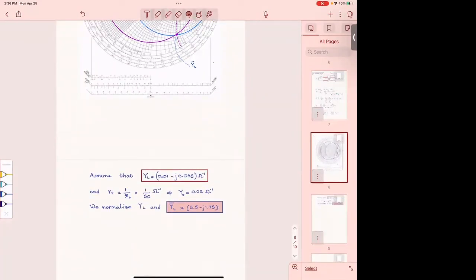I am giving you that the load here, YL, is... you see how small the numbers are? Because that's how admittances are, small numbers. You remember that, all right? Impedances are big in ohms, admittances are small in 1/ohm. So if you see that I give you 100 in admittance, it's a mistake. Or if you find through your calculation something like 100, 150, and it's in admittance form, then there is a mistake somewhere. So small numbers.